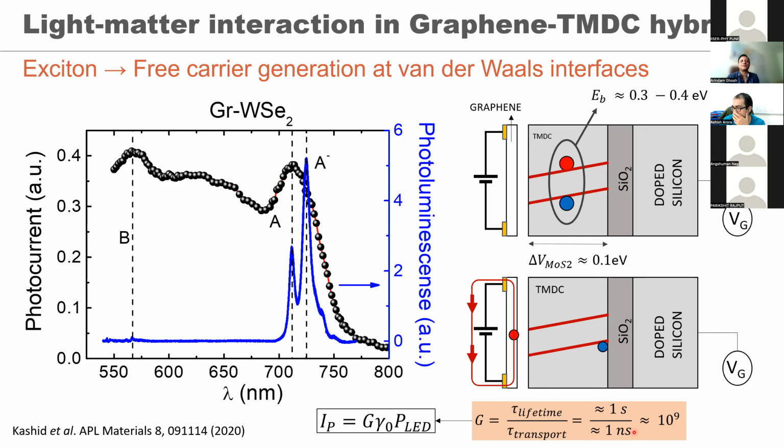Grain boundaries could lead to trapping of carriers. So there are various other possibilities. However, we have done experiments with exfoliated MoS2 but CVD grown graphene heterostructure, in which we found the performance is almost identical. So it's very little difference. But what happens with the chalcogenide which is CVD grown is something which is not very clear to me. But I'm guessing it will lead to a significant reduction in the responsivity, although how much, I don't know.